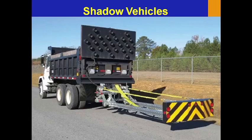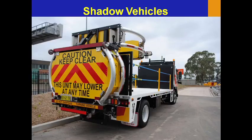They are usually parked in front of the work zone or at the starting of the work zone, which gives an indication to the workers and the road users that some work is going on. Another kind of shadow vehicle: shadow vehicles are used in moving operations to protect work vehicles and workers from traffic approaching from the rear side. The rear side is facing towards the moving traffic. They are moving trucks with attenuators spaced a short distance from the operations.